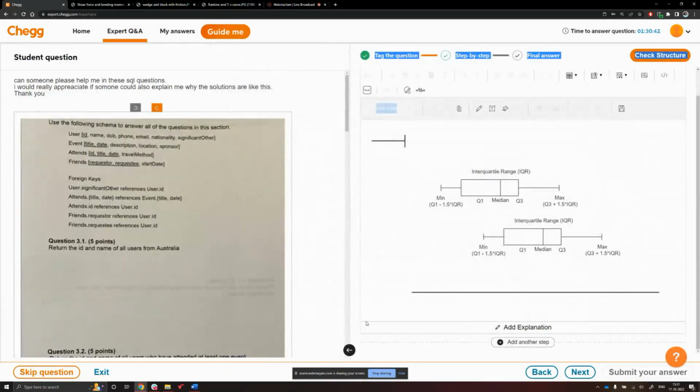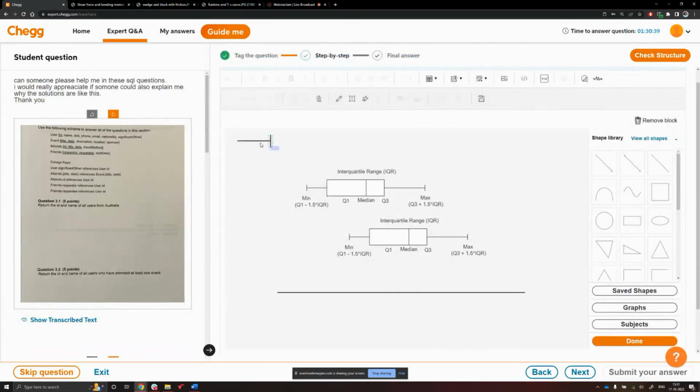So you can, you have to group it first. You can move it, keep it here, then Control C and Control V, and then this actually snaps on the vertical line. So this is one way to draw lines of equal intervals instead of drawing approximately. So this is how you divide the line.